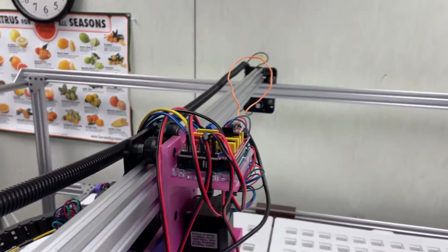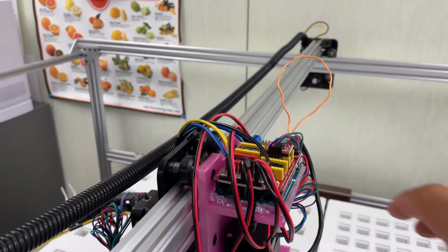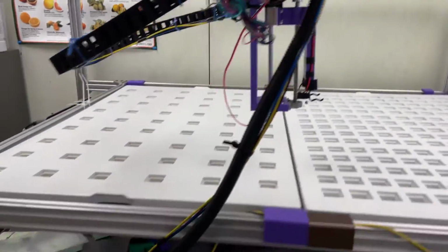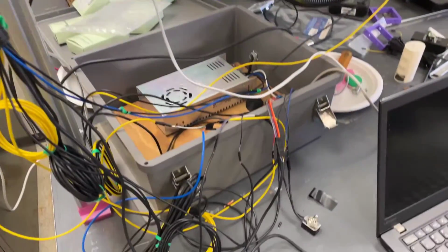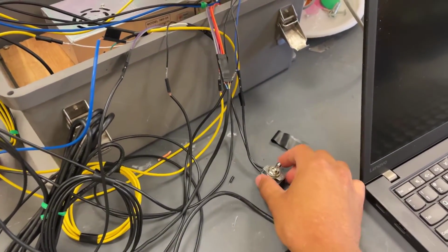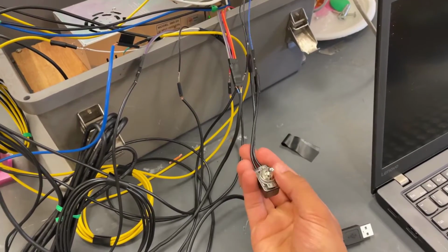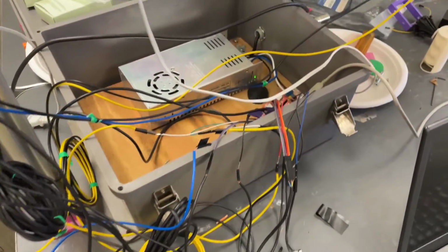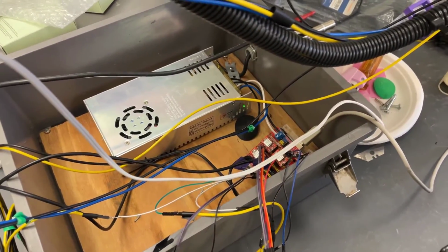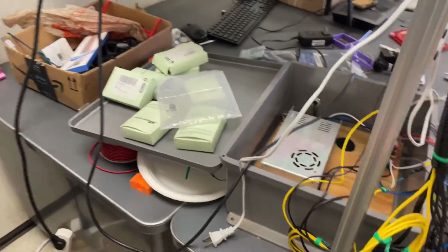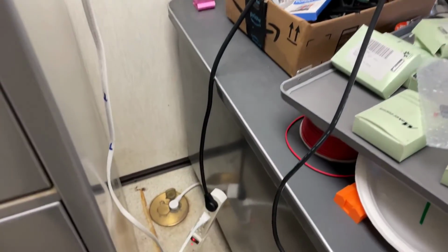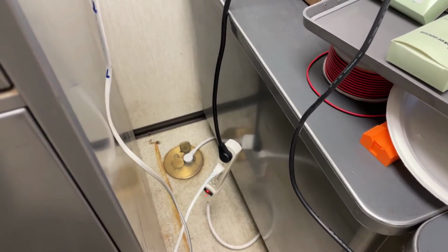Make sure that the connections on top of the tool head are as they should be, especially this jumper cable for enabling the tool head in the first place. Additionally, make sure that the master switch for the frame itself is set to the on position. Ensure that these connections in here are as according to the manual. Ensure that the power supply is plugged into the extension cable, and make sure that the extension cable is plugged into some kind of power